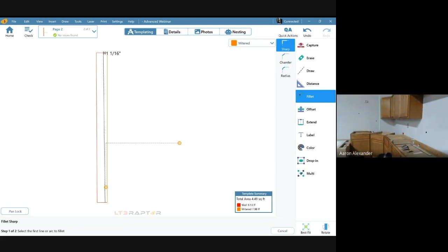third hand, you know, my roll of blue painter's tape, right? So I do love to carry a roll of 1-inch blue painter's tape. We never shoot lasers onto this. We just use it for our third hand. We always shoot lasers on the sticky dots, not blue tape, okay? I just use blue tape to stick things up here. So what I'm going to do on that long run, it's going to be kind of hard to hold that target up there and shoot it with the laser, right? So that's why I say this is my third hand. We get the third hand out. I'm just real simple. Going to stick a piece of tape across there.